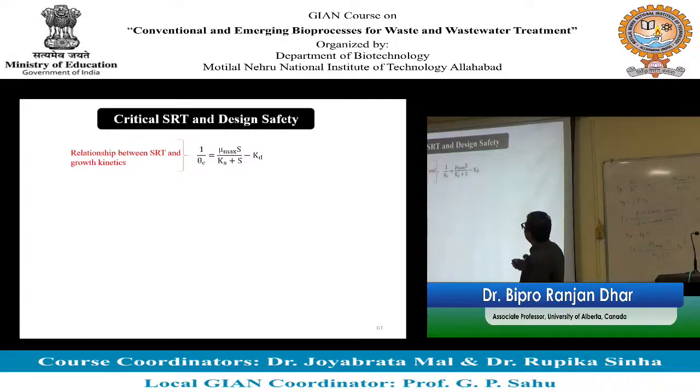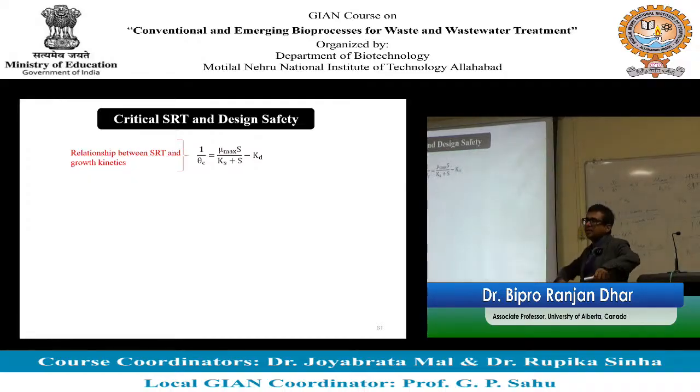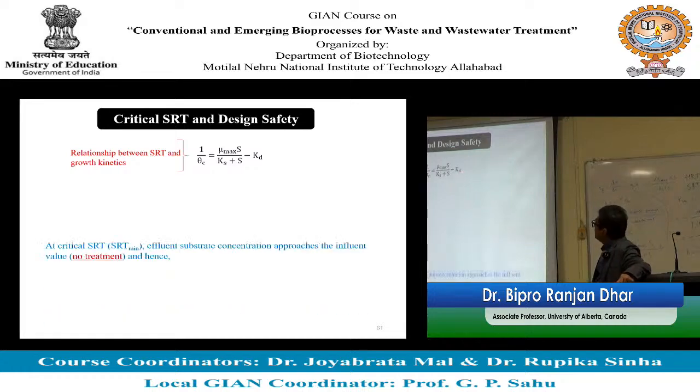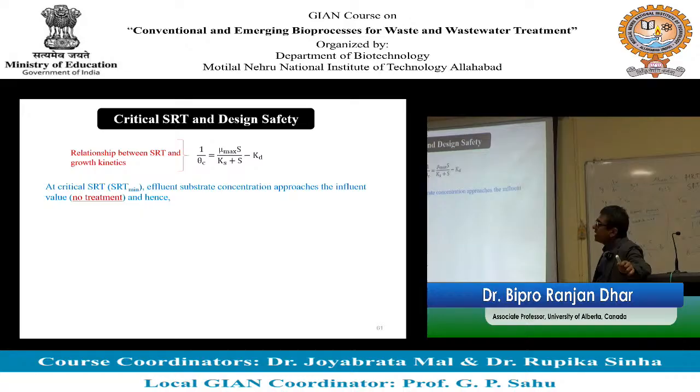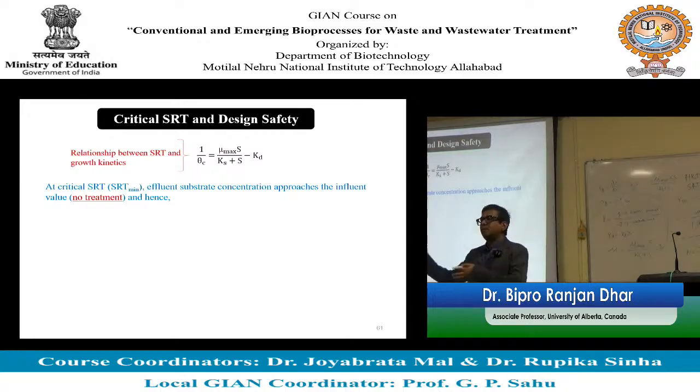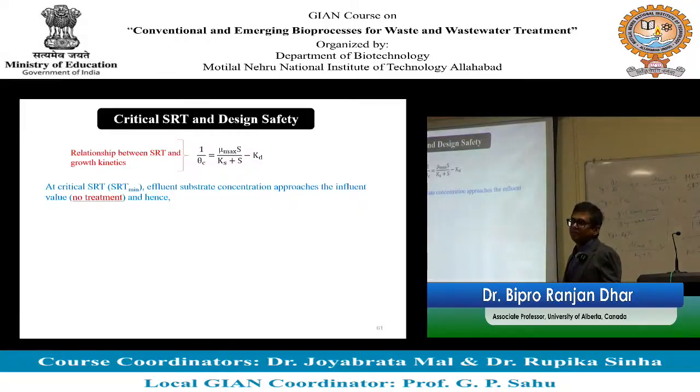So again we have this equation, from one of the previous slides, the kinetic equation. So we have SRT, we have mu max, we have S, we have Ks, we have Kd, right. So at the critical point, and critical point means no treatment. No treatment means your BOD in is going to be BOD out, right? No removal of BOD. So S is going to be the same as S naught.